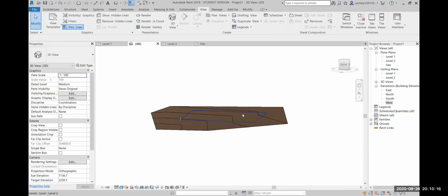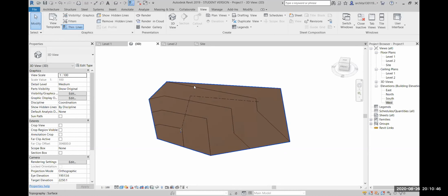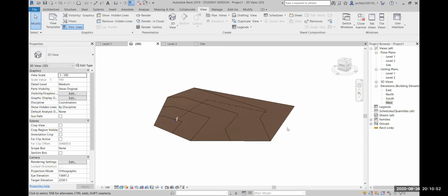Levels. The level difference. It shows the slope and the level difference. Basically, there are points on the slope. All the points which have the same elevation will connect together and create one contour line. Over here, this is the line which has all the points having the same elevation. That is what is meant by a contour line, and that is the important role of elevation when you are dealing with the site.